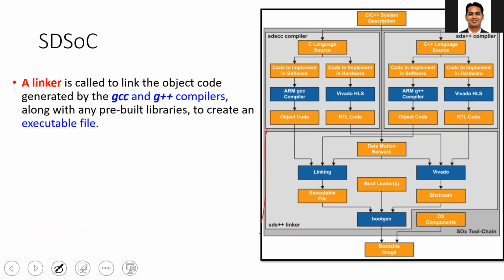Then you have the SDS linker, which takes the output of the compiler and Vivado HLS to create a file which can be used to program the SoC.